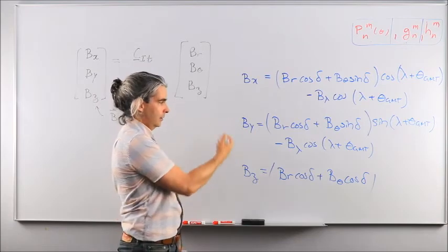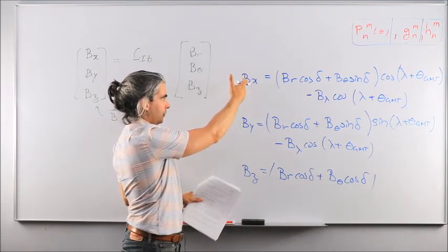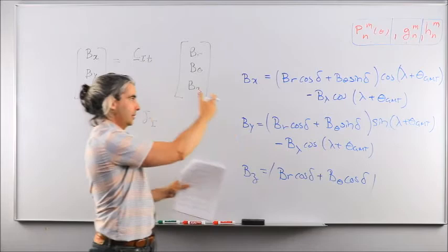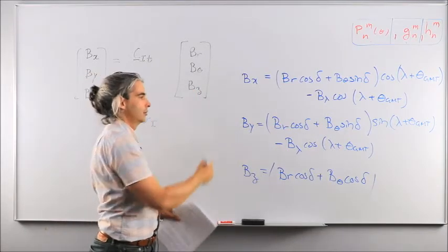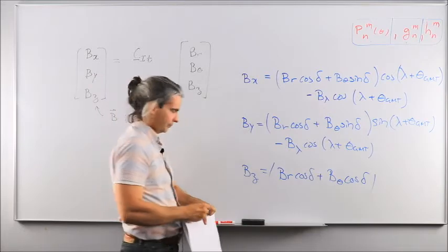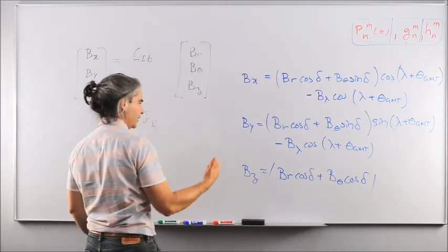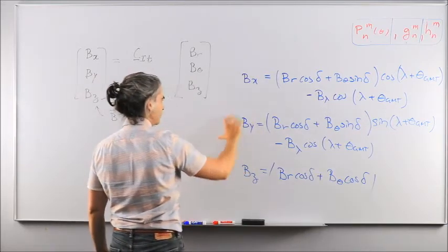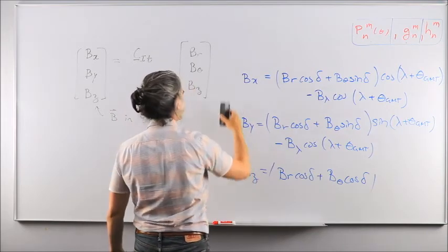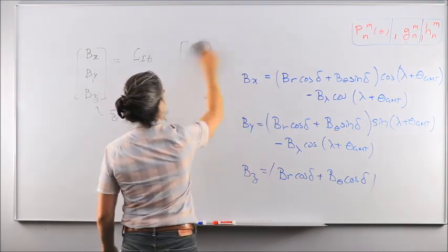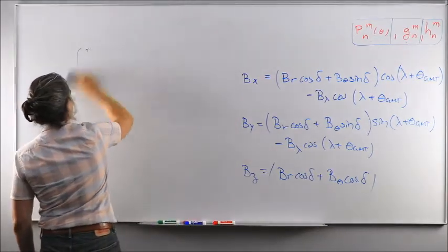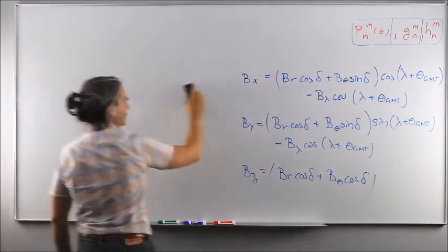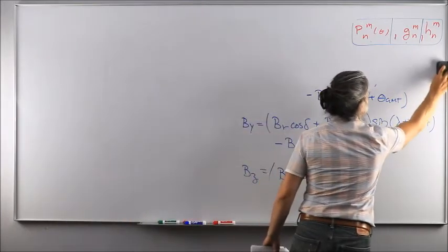And then you take either this set of Bx, By, Bz, or the simplest one we're going to derive today, and then we're going to go from this to body fix, okay? Because I don't want to repeat the conversion from ECI to body fix whenever I present a new magnetic field model. We're going to save that for later once we have selected the appropriate model for the magnetic field based on the accuracy you are looking for.